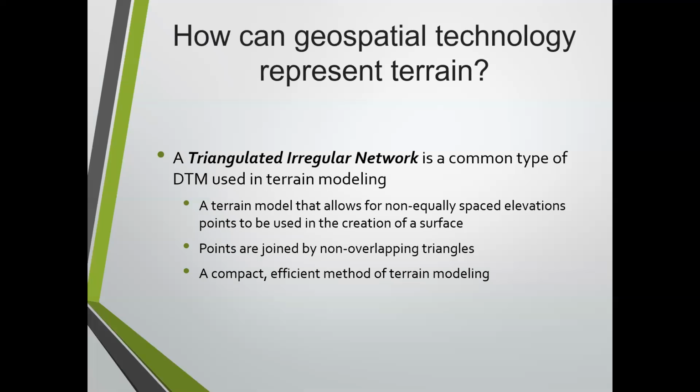I do. Yes. You know that if you just take a bunch of raw points and you dump them into, say, a program like Civil 3D, you're going to get a TIN out of it, but it won't necessarily be right until you incorporate your break lines and break line files. Because the triangulation process just finds the points and starts generating triangles. So the fault lines or break lines give it guidance into how it's going to model.